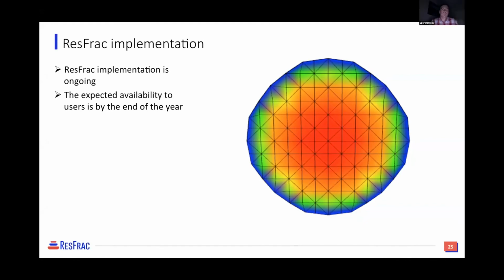Okay, well, here's my answer. These are more like mathematical algorithms. They don't distinguish between granitic rocks or shales. What we need to have is rock properties and mechanical properties, such as elastic properties, Young's modulus, Poisson ratio, fracture toughness, and so on. And stress, and some other properties.